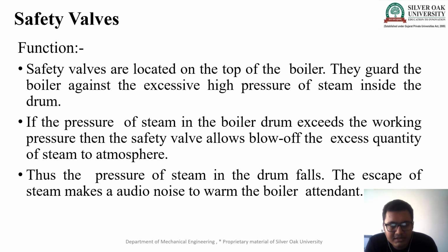So if the pressure of steam in the boiler drum exceeds the working pressure, the safety valve allows the excess steam to blow off to the atmosphere to save the boiler from overheating and explosion. Thus the pressure of steam in the drum falls, and the escape of the steam makes an audible noise to warn about the boiler.